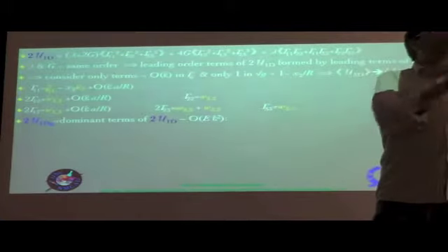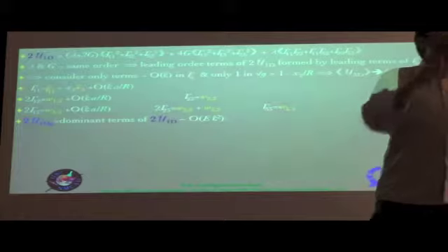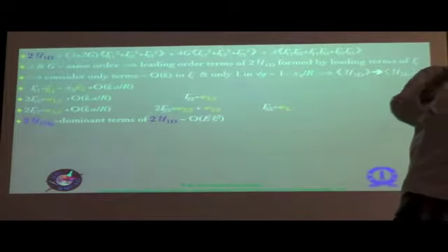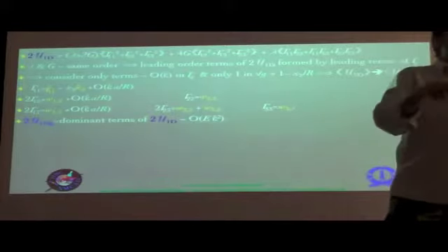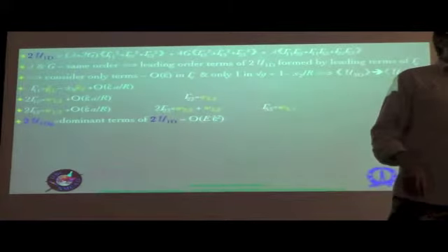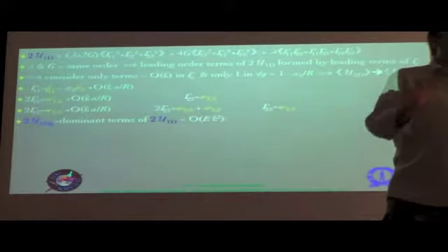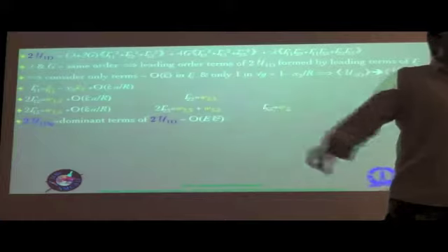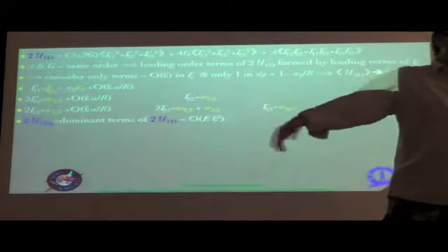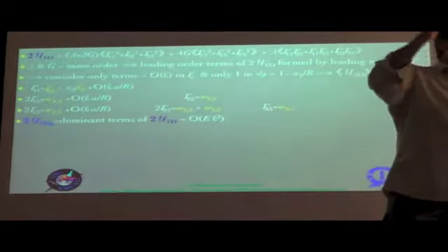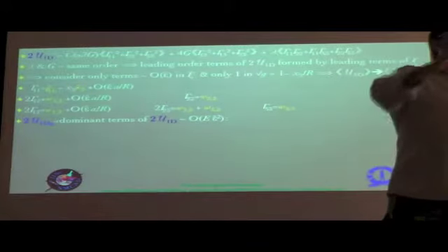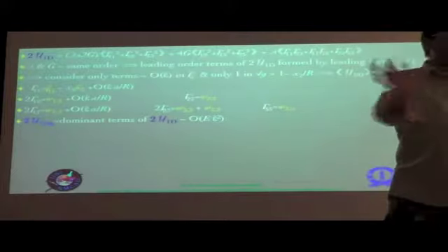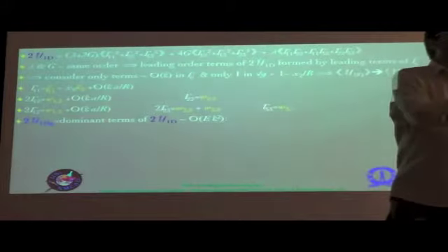We are only talking about terms within the integrand. So we can do that multiplication of half gamma transpose times D times gamma, right? So that 6 by 6 matrix multiplies those six element strain vectors on both sides, and then basically you have that many terms expanded out. Basically in general 36 elements, of course not all are independent because of the symmetry of D, which is basically involved. So you have 21 terms in general, for example. Then you have to sort out which are the leading terms.